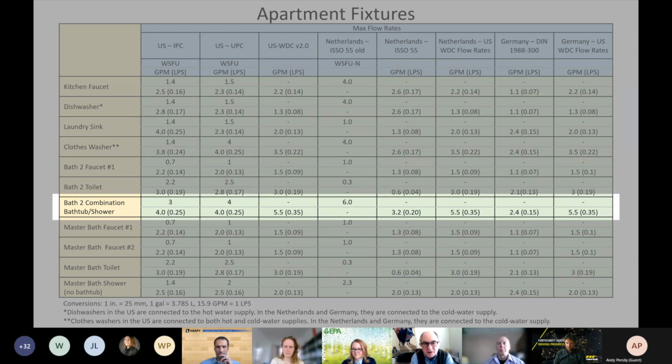I actually saw an installation of one of those very large garden tubs in a home some years ago with 3/8 tubing connecting it, and they were wondering why the water came out of the tub filler at such a dribble. Well, it had no choice. It had this great resistor in between the tub and its trunk line. So it took a really long time to fill this really, really big tub. I have no idea why the plumber put that in. Can't figure that out at all.